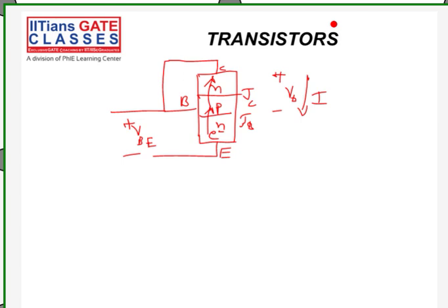Right? So these electrons then cross the collector junction due to the built-in potential present across the collector junction. Thus, the current flow takes place through the collector junction, even though the collector and the base terminals are shorted together. Okay, so that was the concept behind this. Collector and base terminals are shorted. Even after that, the electrons are reaching the collector junction.